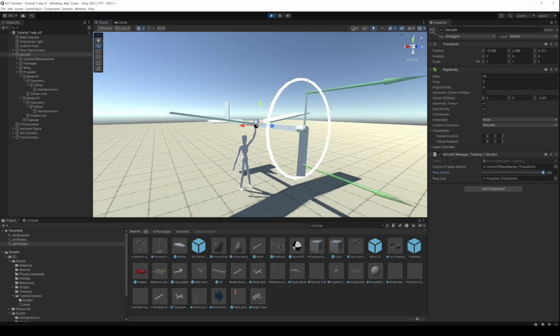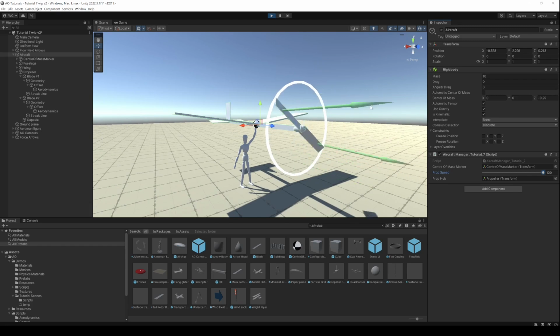If in your project settings you don't have a fixed time step of around 0.002, you'll find this gets pretty chunky when you're running fast propeller speeds. So when things are rotating fast, you do need to be able to use a small time step, else the propeller goes around an awful long way in each step.